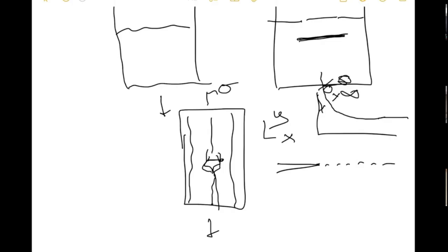The theoretical stress of a linear elastic body at a crack, what's a crack? A crack means a surface where this angle is equal to 0. It's the limiting case where this thing is perfectly two surfaces. That tip is infinitely sharp, and the stress there is actually infinite. And we know in real materials it can't be infinite because something has to give.